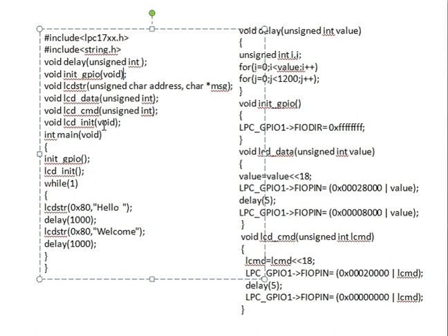Then we use void lcd_init(void). This is for initializing your LCD module. In this we will be passing the commands for initial configuration. For example, if you think the LCD has some data content present in it and I want to clear it, when you're running the LCD program for the first time, you pass some commands to clear the screen, and also set the modes as I've discussed. Since we are using a 16 by 2 LCD module here, even that should be addressed. How many lines? 2 lines. And how many characters?